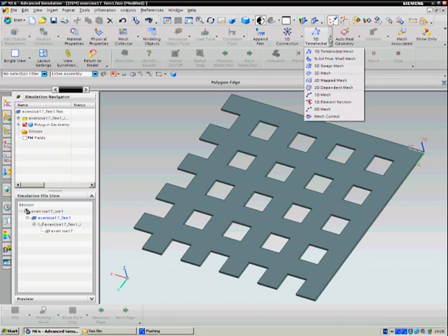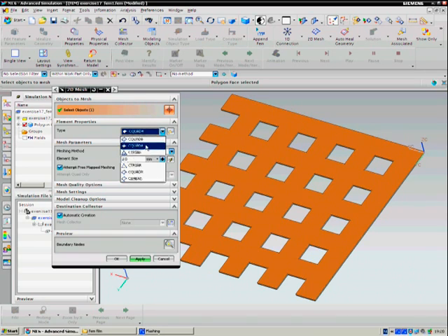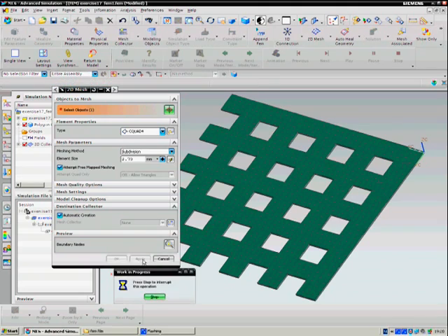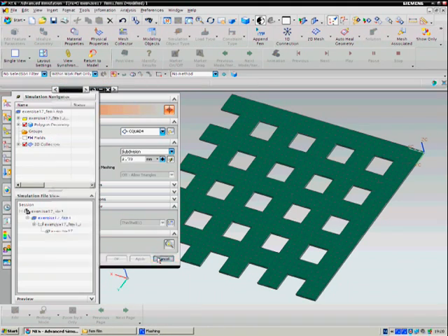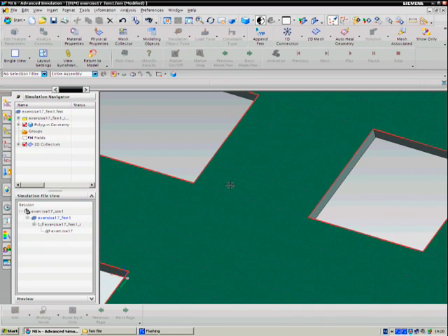We go to the FEM file and apply a 2D mesh. We select the body, the type of elements, and we allow the computer to choose the size of the elements. If you now zoom into the model, you see that the mesh is available.